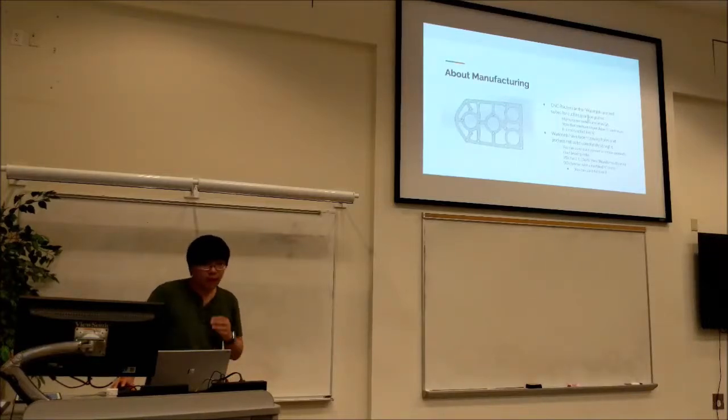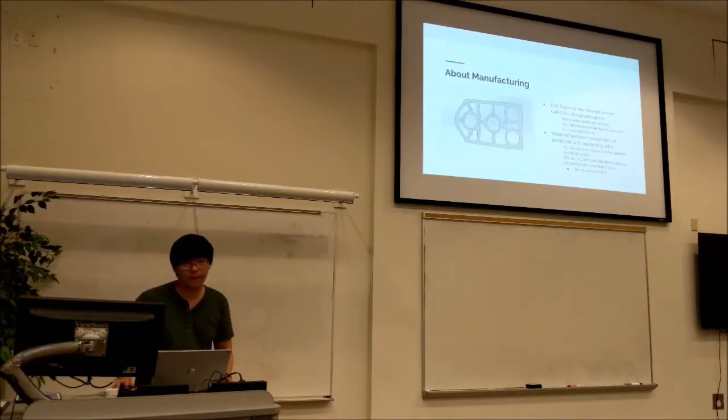So really quick about manufacturing custom gearboxes. CNC routers and water jets are really nice for this. Especially in Georgia, I would recommend water jetting because that can be outsourced and it's free to us. But you do have to purchase the 1/4 inch aluminum plate because it's not supplied like the 1/8 inch aluminum.